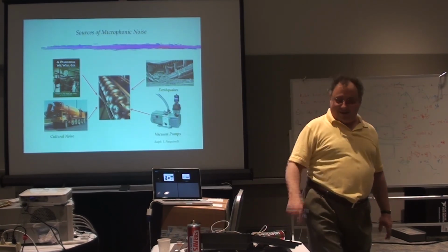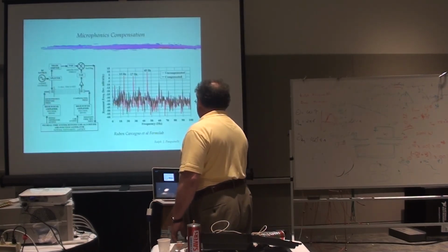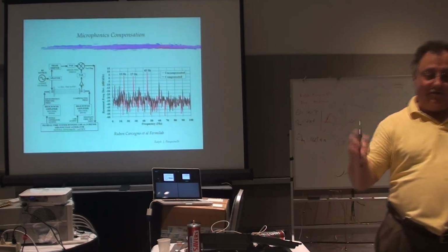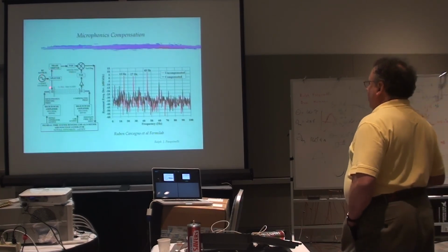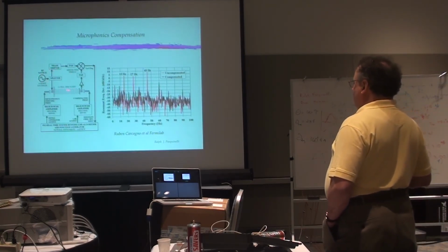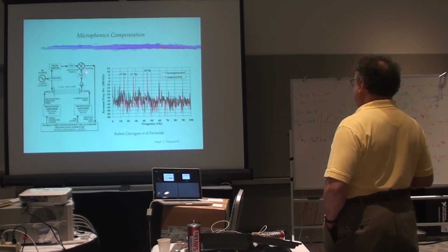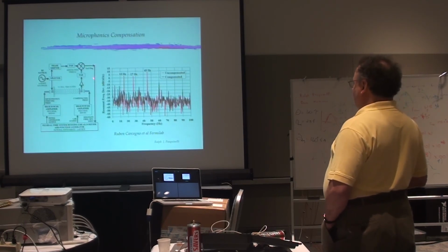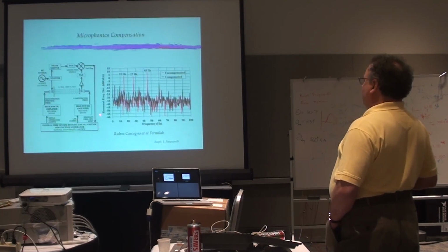So that's a problem. These are all things you have to worry about when you decide to go this route. There are other clever things you can do, and we've got some very clever feedback guys. Remember feedback: you have your signal generator, and then you drive your cavity, which is here. This one says a 13-cell cavity, and you take a little bit of signal back through some kind of directional coupler. You mix the signal with mixers, all the parts that we're teaching here. You take that error signal and go into this sneaky little black box with FPGAs and everything else, and what it does is provide negative feedback.